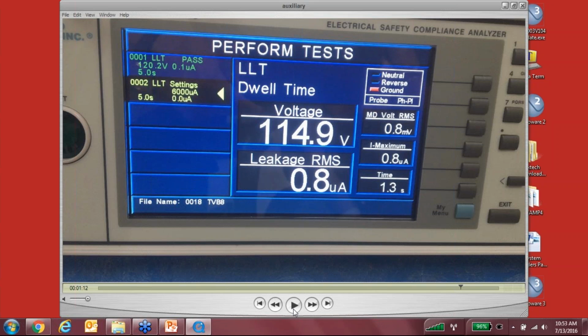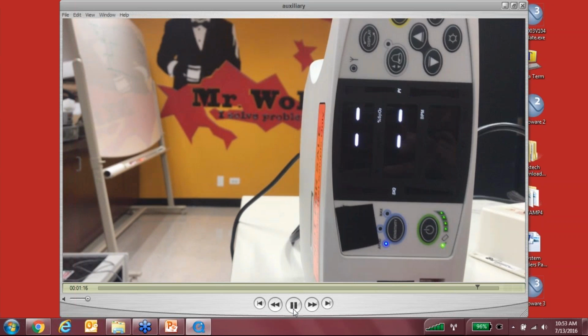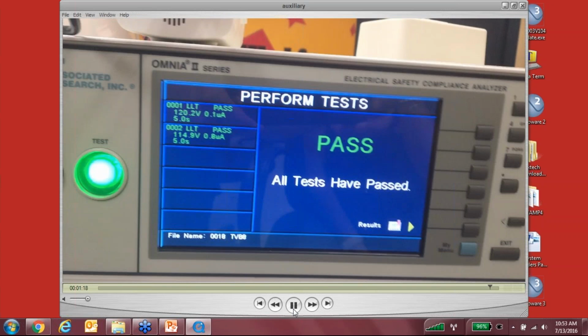So if anything, when you're running your tests, that's a principle that you should be abiding by. Or if somehow your ground closed, or you're seeing the same leakage values when ground is open and closed, that can be a red flag. You want to double check your connections. You want to make sure that when ground is open, you should be getting higher values than when the ground is closed. I mean, that's not to say it's all the time. Maybe your insulation is tip-top and nothing leaks through, so that's definitely another scenario. So again, DUT is on, and we've passed.